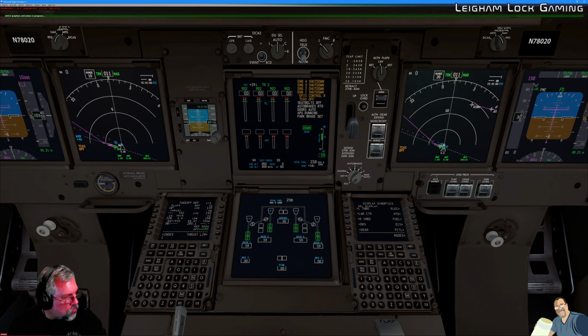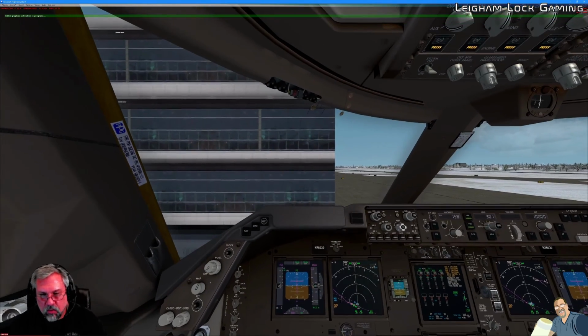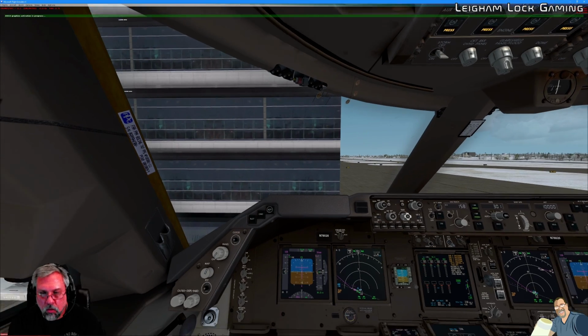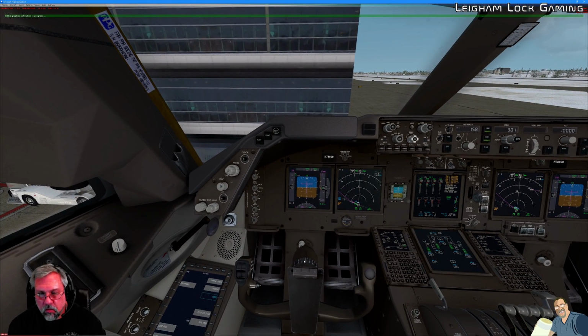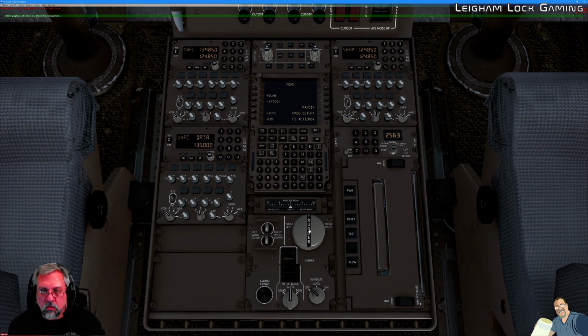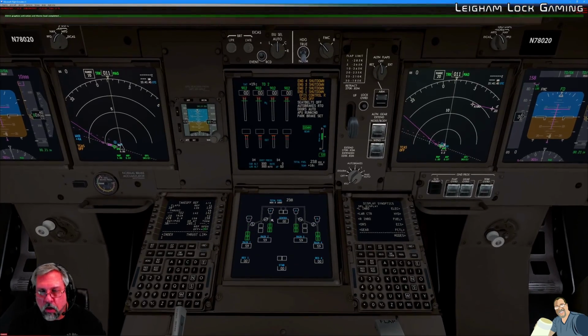Aileron trim and rudder trim should both be set to 0. You can tell the aileron trim is set from the captain's seat if you look right at your flight stick. The aileron trim would be represented here by a change in position of this flight stick, and that's what these numbers indicate up top. We're evened out, so it's set for 0. We don't have any trim one direction or the other. And then the other one is over here on the aft pedestal. Rudder trim is set to 0, and that's where that needs to be. So at this point, we are ready for our next checklist.